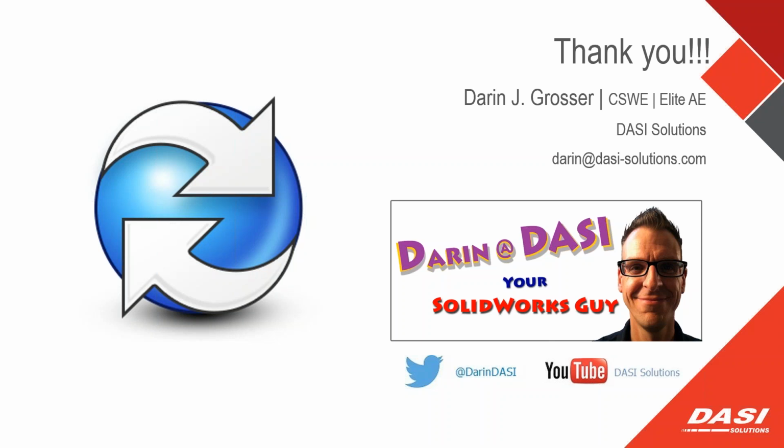Can you rename a workflow state after it's created? You can, as long as a file hasn't already gone through that state. What I basically mean by that is if a workflow state has been placed there, there is a historical marker in a file that's gone through that transition. So for one reason or another, you can't delete the state at all. So a lot of times it's a swap out or a swap in of that particular workflow state, or creating another state that's got the name and then trying to swap those names out. But that can be a little tricky. So there's where your nomenclature definitely, you want to make sure that you test that through before it goes full production on the vault.